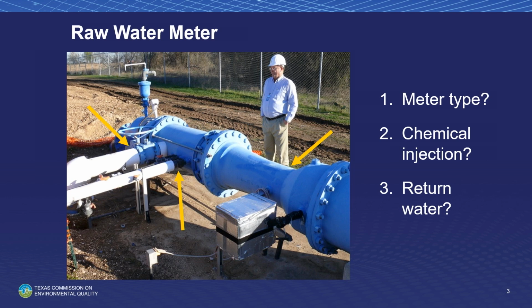Well, what kind of problems can you run into with meters? Well, first of all, if you're doing any kind of return from your ponds, the return from those ponds should come in ahead of the meters. If you're going to do treatment in a plant, you've got to know what the total flow coming into the plant is.